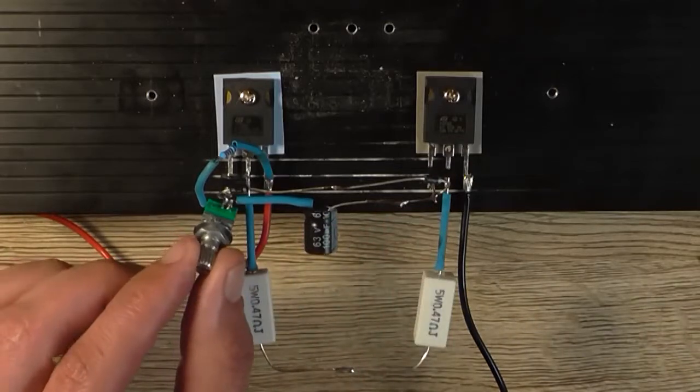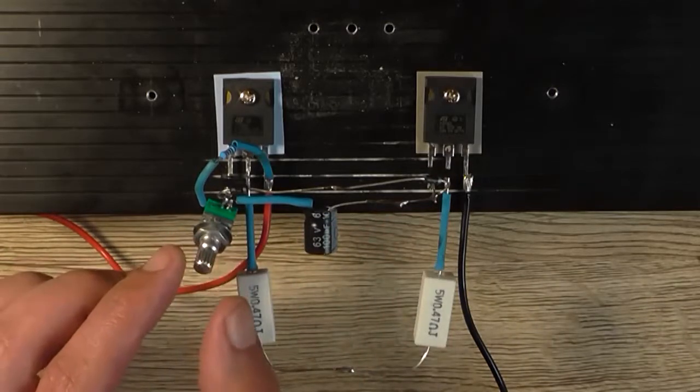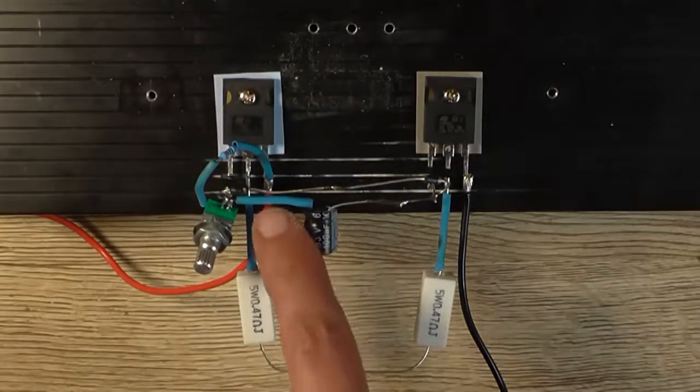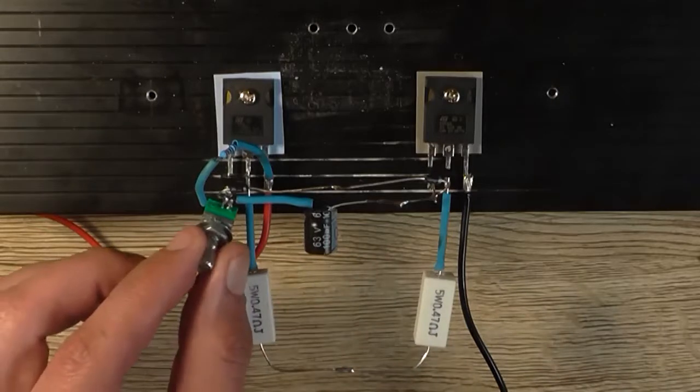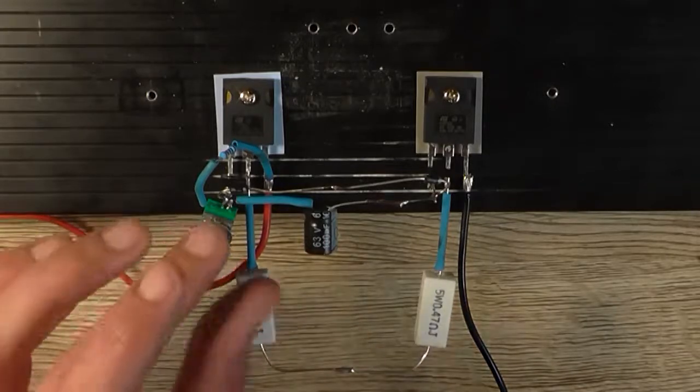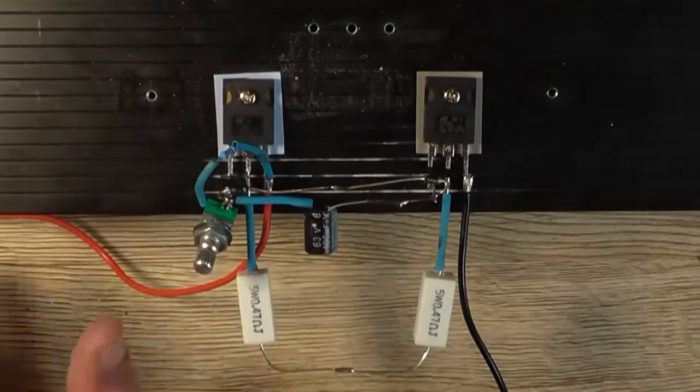This is our biasing adjustment pot, which is a 50k linear, with a 2k2 resistor there, which is connected directly to the positive. And I've set that around to about halfway. And reading the original description of this particular circuit, when the pot was set in halfway position, the amplifier performed fine, so it's probably not even necessary, but we'll have a look at how that pot affects the output stage.